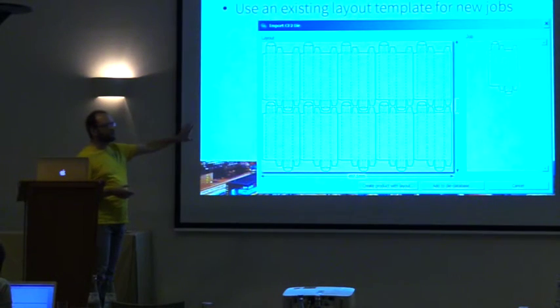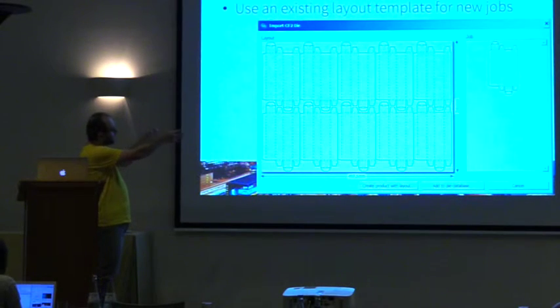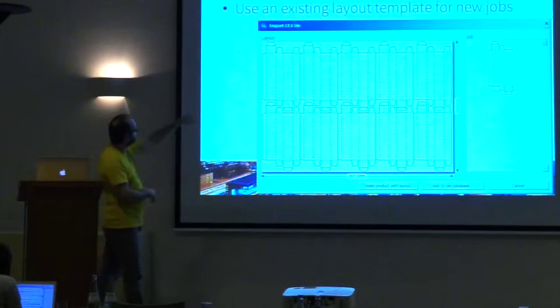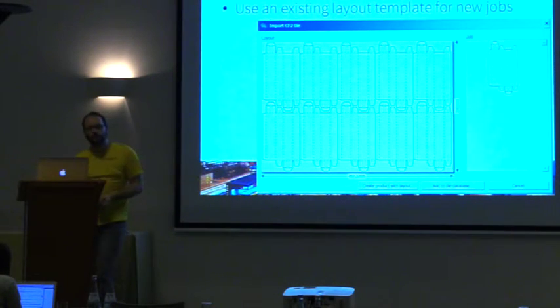You tell IMP that you want to use this configuration, so you don't give it any freedom in how the items are arranged on the sheet. You simply tell it to use this, and then IMP will look at what jobs you have and how many of each job that you want to print. And it will calculate a solution where everything uses this particular layout. Typically, those are CF2 files. You import them, and then you do your planning with that.